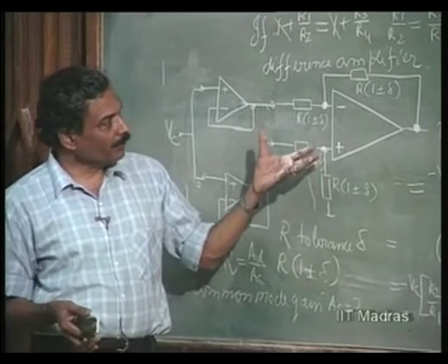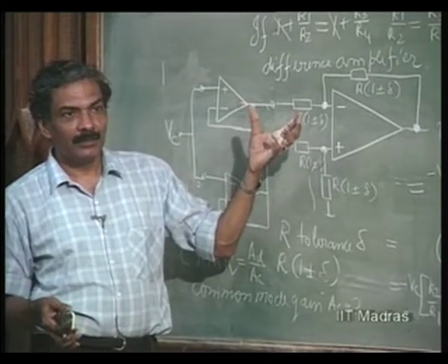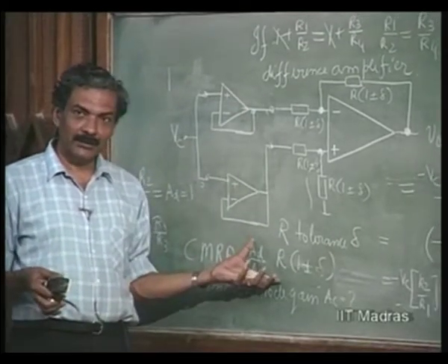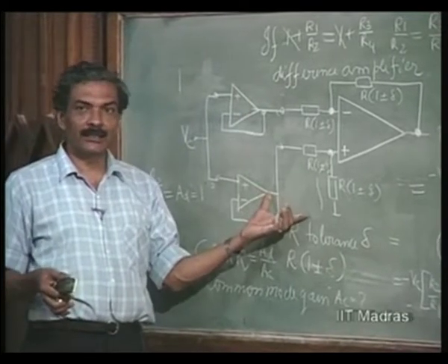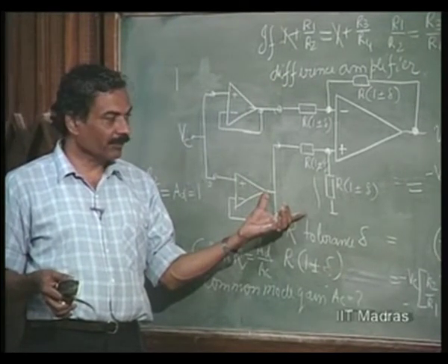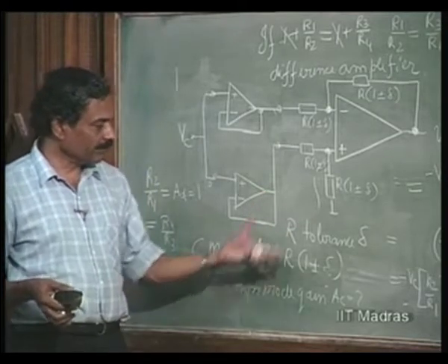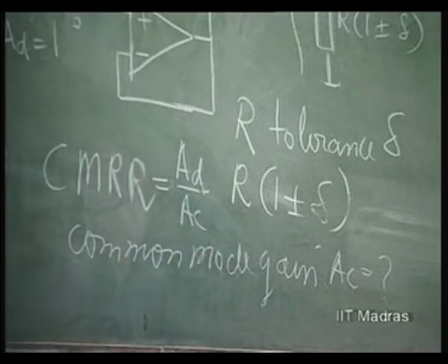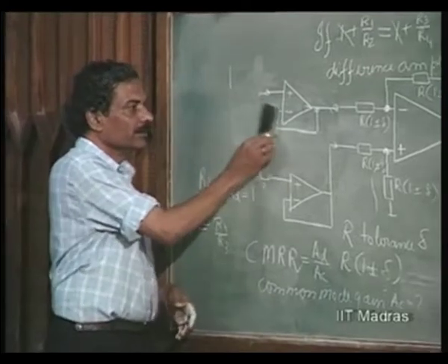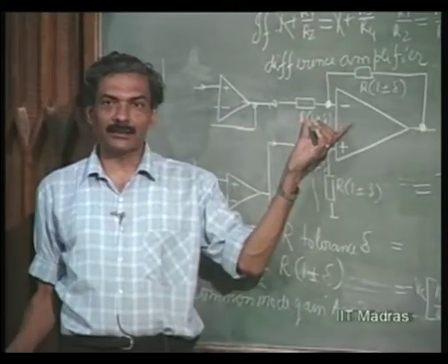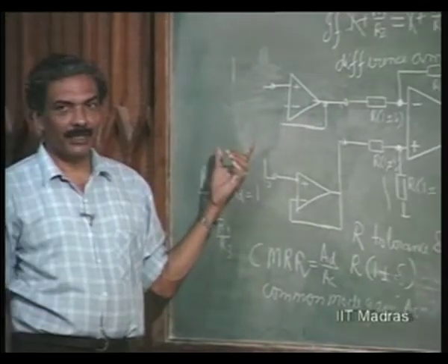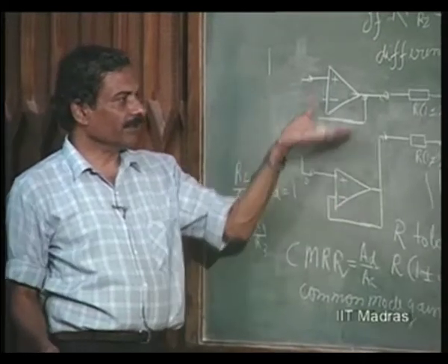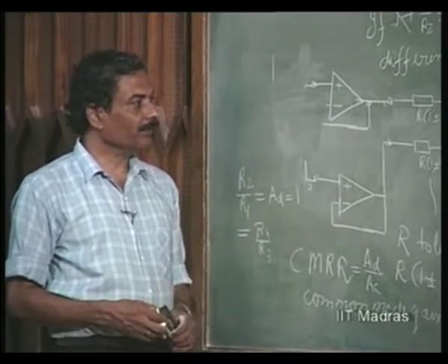Okay. So, in order to make the instrumentation amplifier be sold at low rates, we must use off the shelf components, without further testing the instrumentation amplifier. In such a situation, we must accept certain tolerance for these resistors. So, how to improve the common mode rejection ratio? This is important. How to use poor tolerance resistors here and still get better common mode rejection ratio is one thing, and how to buffer, that we have already discussed, is going to be the topic for the next class.